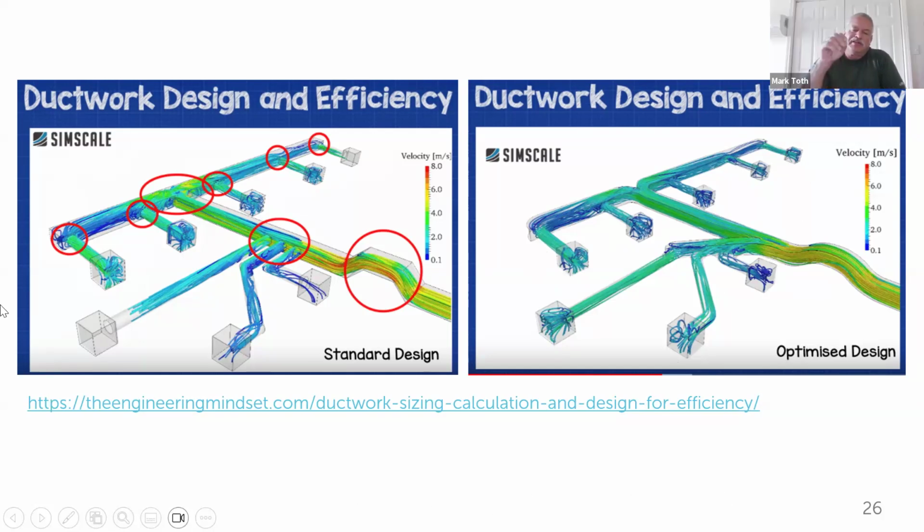That's a great place to throw in: earlier you mentioned using dampers either at the outlet where you can adjust it or dampers in line in the duct. If you happen to end up with something like on the left and each of these runs have a damper in them, you can overcome the problems in that system by adjusting your dampers, because you're then going to be able to take areas where you're getting too much air and damper them off to force more air through the places that aren't getting air. So dampers or adjustable outlets are extremely important for balancing a system.